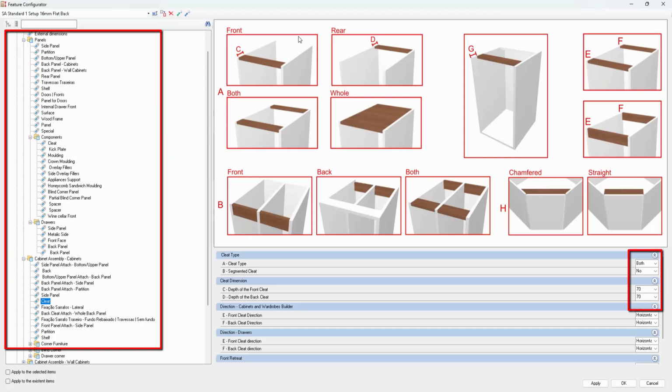I tend to just use 70 for the reason that when you're going to put a sink in, or you're going to put a hob electric stove cooktop in, usually at 70 you don't have to cut them or adjust them at all. But again, that's all down to how you put yours together, so you'd be able to adjust these sizes to whatever system that you are using.